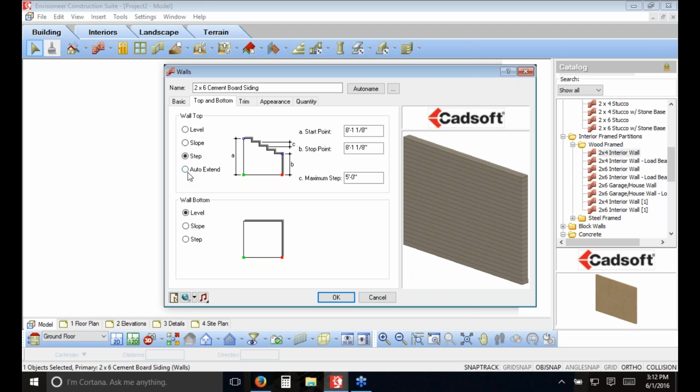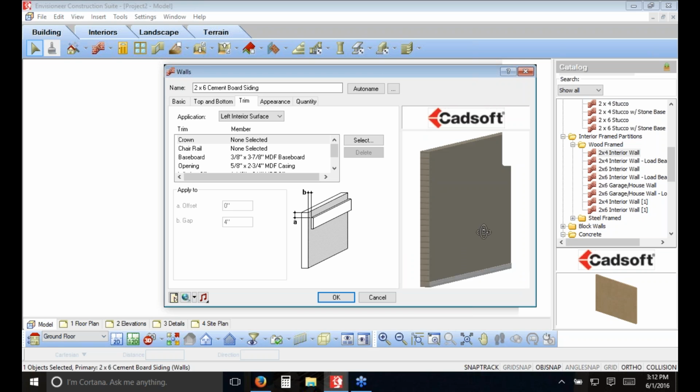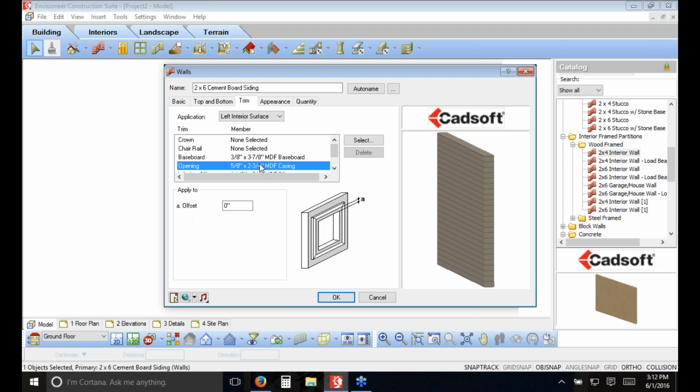As we're drawing the wall, it's also putting in trim. So if I turn this wall around to look at the inside face of it, you can see it's already got baseboard. And when I drop in windows and doors, it's automatically going to case around them as well. And I can also include any kind of exterior trim. So if you have any exterior trim that you like to include when you're doing siding, that all can be included. So as I'm drawing the wall, that's automatically ticking off and calculating the quantities that you have for that trim.